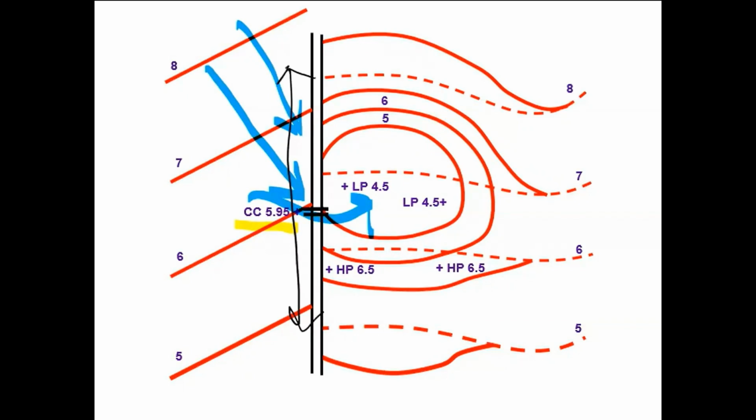And the reason that becomes an issue is that where we've located our curb cut here, water clearly flows because the elevation of the curb cut, which is absolutely determined from the parking lot, is clearly above the low points in the retention area.